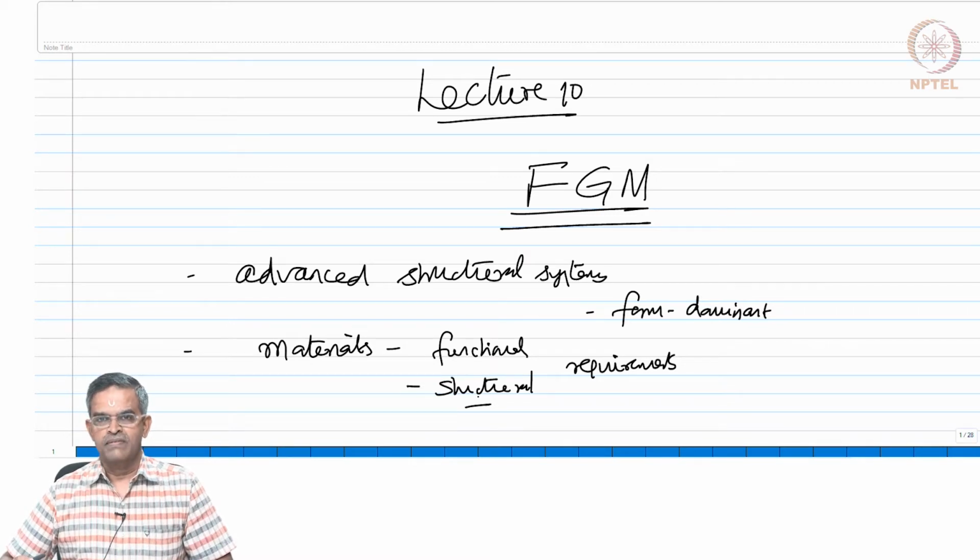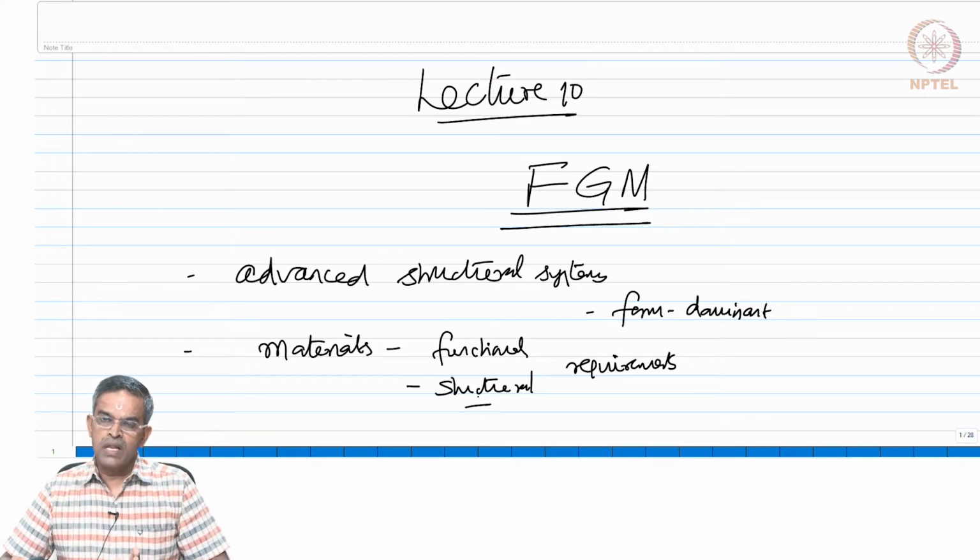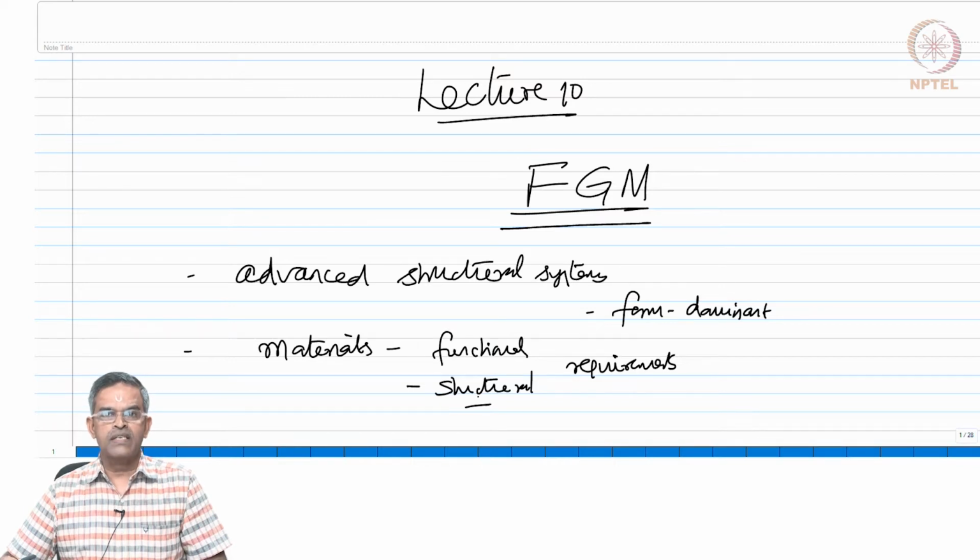So, advanced steel design is dealing with two aspects of the design procedures. One is the geometric centric design, where the structural assembly takes care of the load acting upon the structure, apart from the advanced design procedures such as plastic design, etc. In addition, we are also looking for a material which is compatible with this large displacement structural systems. What does it mean? The material should possess enough ductility. To adopt plastic design, the elastoplastic domain of the material should be very dominant. To have good toughness, the area of the stress strain curve should be large enough. The material should exhibit ductility, etc.